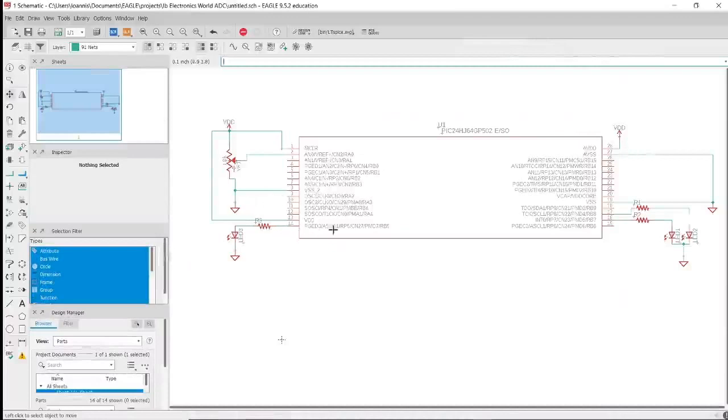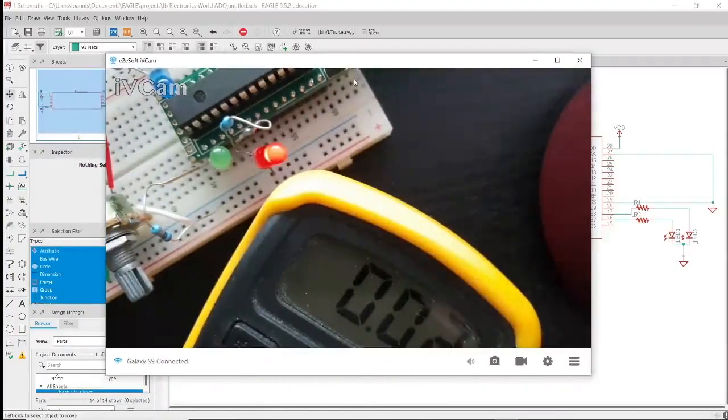So you can see that the RB, we are using a resistor 330 ohms and LED, and we are using again 2 resistors and again 2 LEDs which are connected to the ground, and we have also powered everything on the PIC microcontroller, and we are using a potentiometer which is connected to the ground and to the plus 3.3, and it's also connected to the analog input pin RA0.